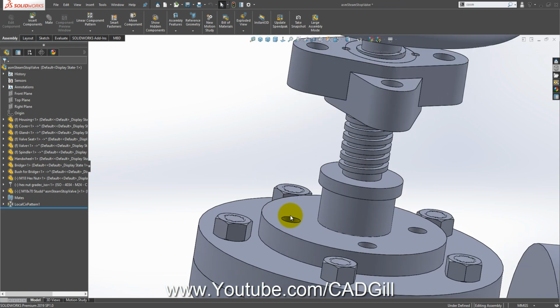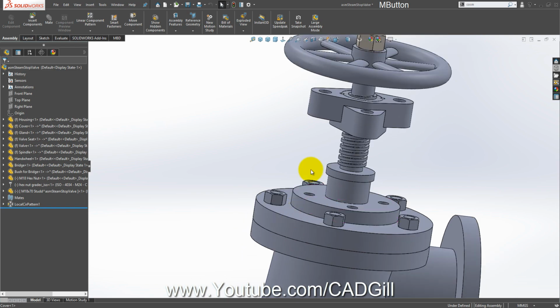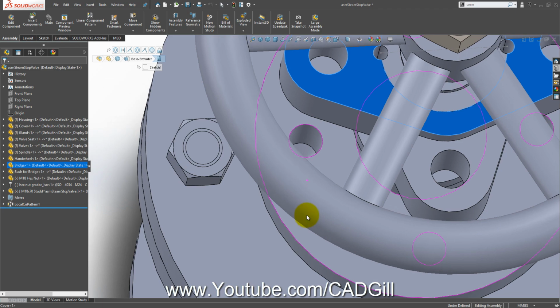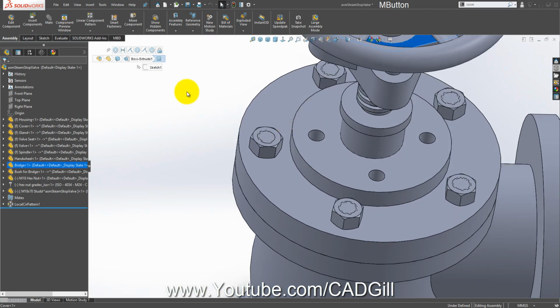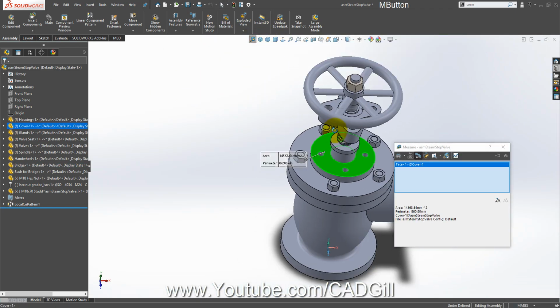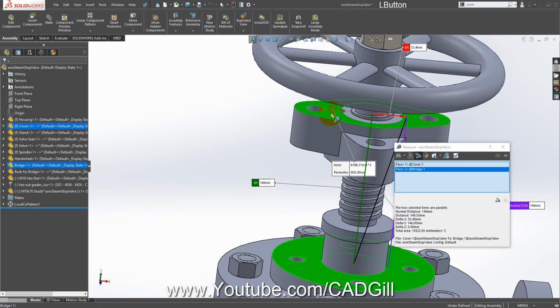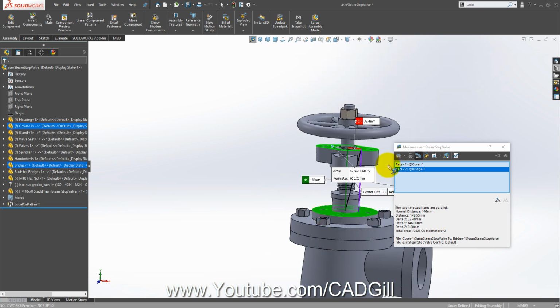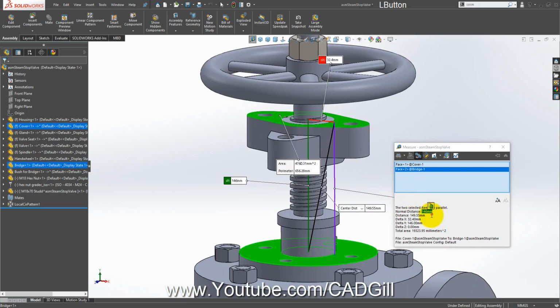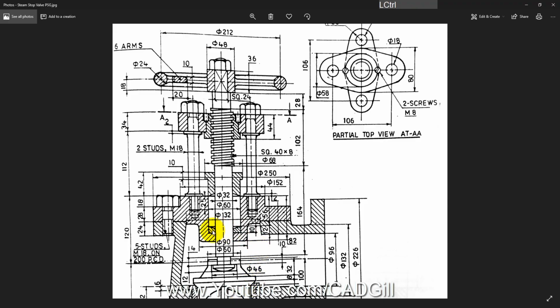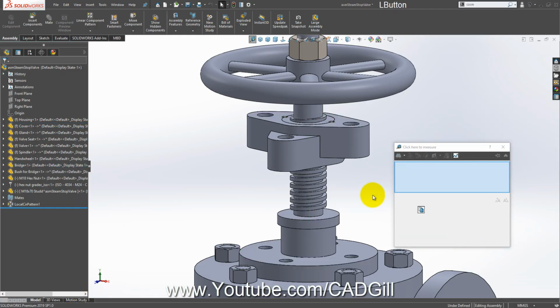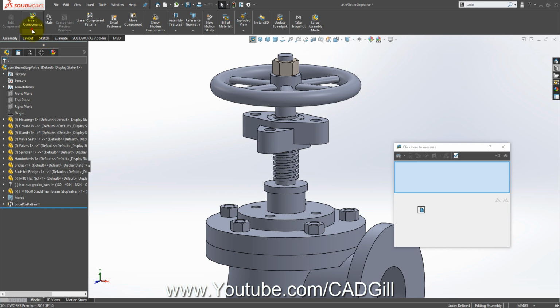From this till the inside of this. Let me measure the dimension from here till here. The distance is 146 mm. 146 plus we have to keep in mind that there is a tapping inside, 25 mm. So let's create a stud here, keeping that in mind.